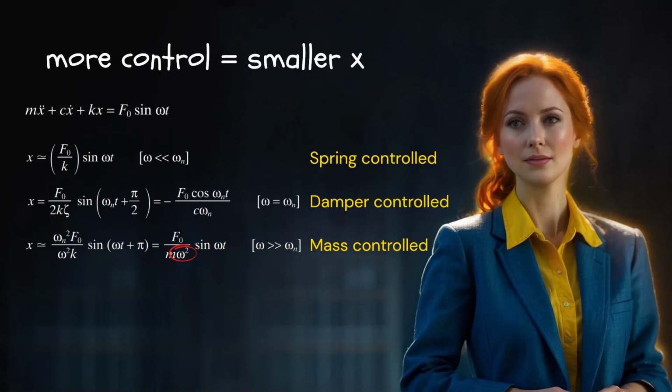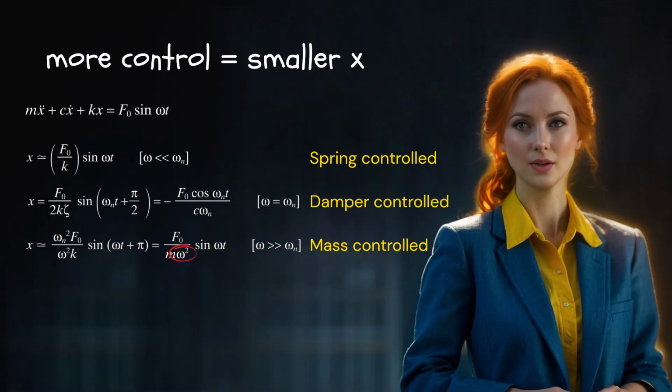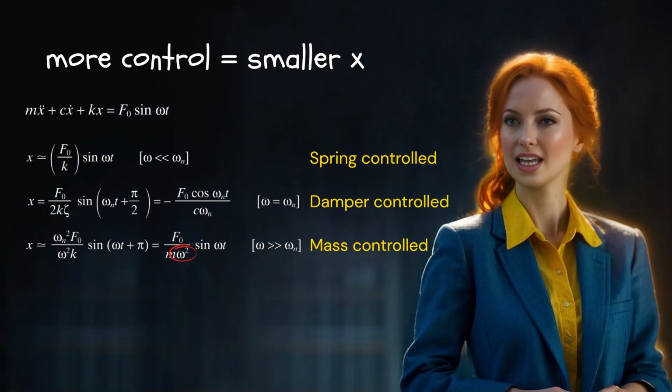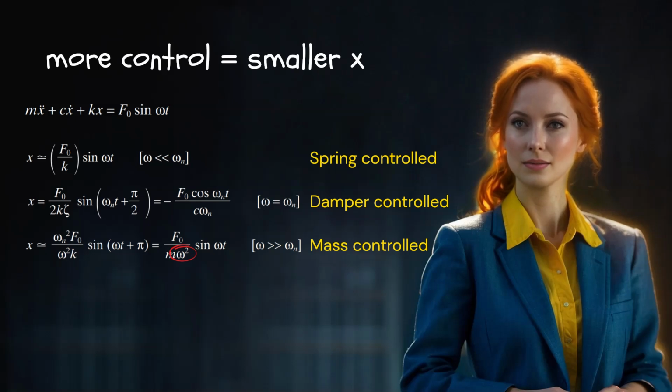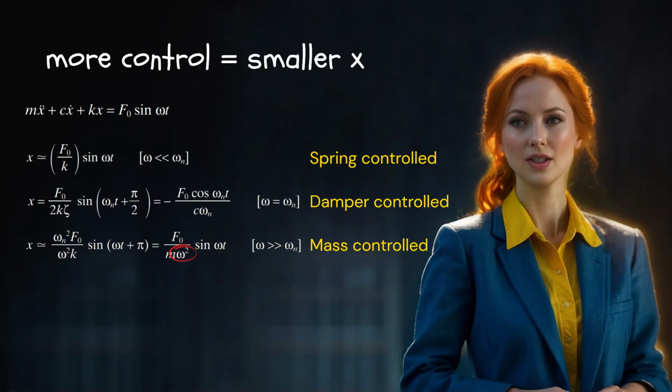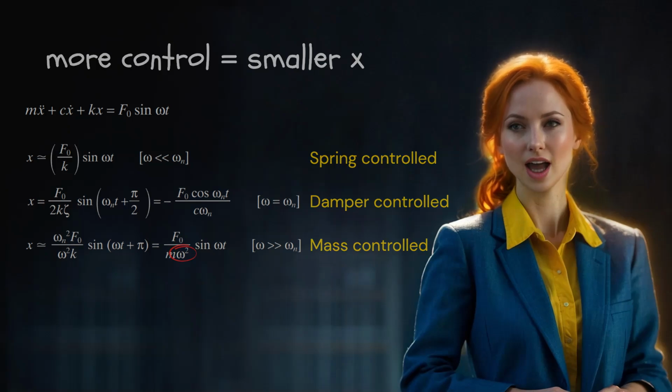Resultingly, the spring term, kx in the above equation, dominates at low frequencies, as its magnitude remains unchanged while the importance of mass fades out. This means that at low frequencies, the spring plays the primary role in limiting cone movement, and the excursion is governed mostly by the spring force.